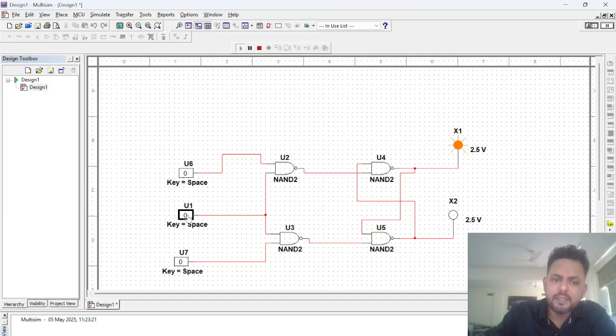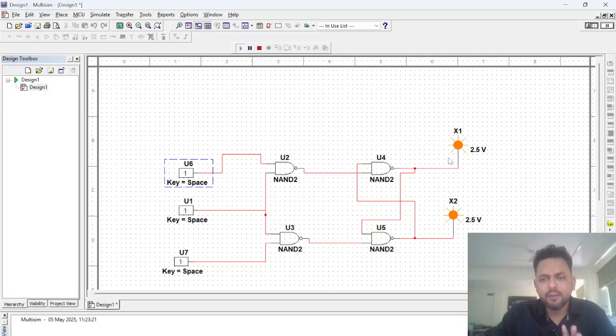When the clock pulse is 1 and both values are 0, we get memory. But as soon as we change it to 1 0, we get Q 1, Q bar 0. When I change it to 0 1, we get 0 1 here, that means Q becomes 0. And 1 1 is an invalid state. I hope you understood till here.